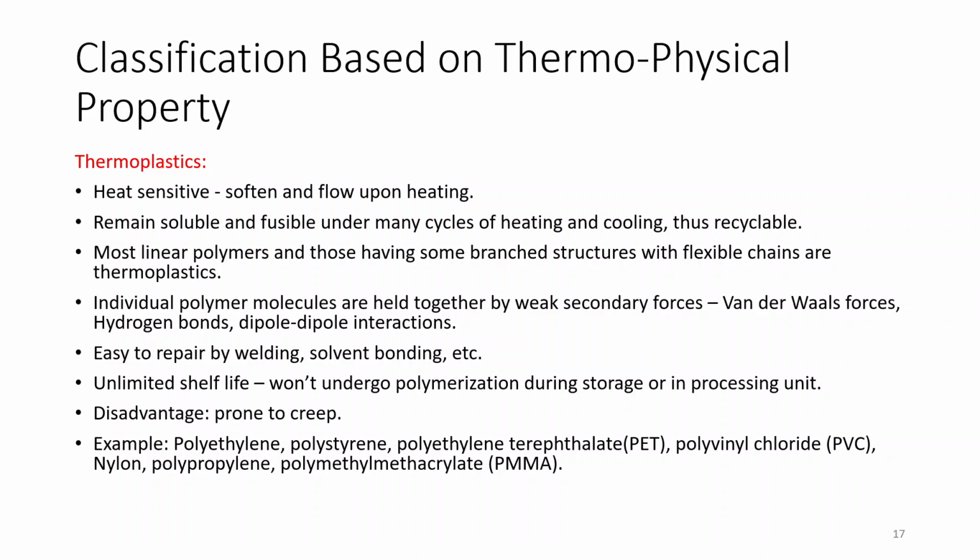Next is classification based on thermophysical properties. First we have thermoplastics. In this case, you have materials which are heat sensitive. These soften and flow upon heating. These remain soluble and fusible under many cycles of heating and cooling. Thus, they are recyclable. Most linear polymers, and those having some branch structures with flexible chains, are thermoplastics.